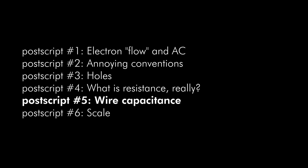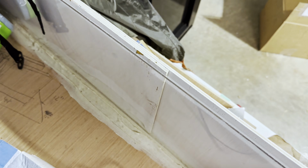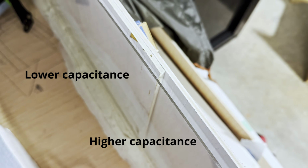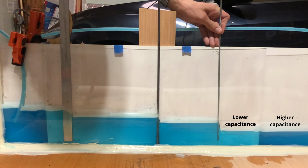The water trough model handles the capacitance of the wire itself really well, which is, I think, something that's pretty rare in electrical analog models. Capacitance is actually defined as a charge per voltage. It's literally how many electrons you need to add to a thing in order to raise the voltage, raise the water level, by a certain amount. In reality, this number is all over the place and varies significantly down the length of wire depending on what's around it. In the water trough model, the capacitance isn't constant everywhere either. Near the ends where the tube comes in, the channel is actually thicker. The capacitance is higher here, and the amount of water or charge per length of trough is higher, but the water level, the voltage, is the same.